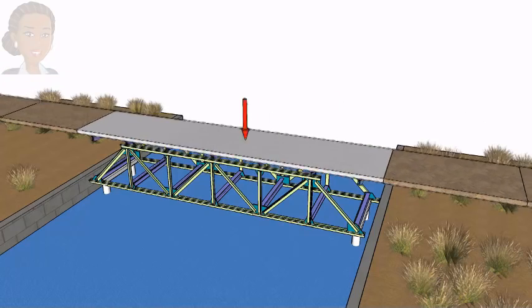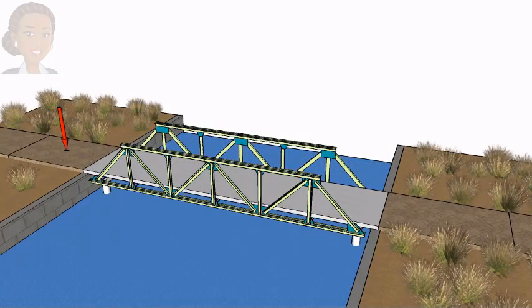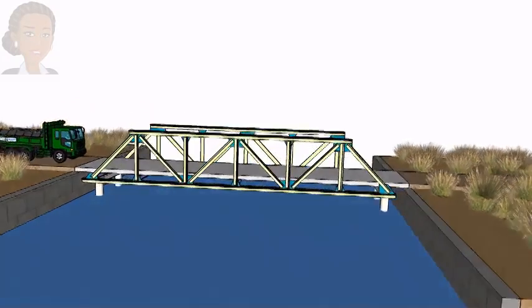We use this moving load pattern to construct the influence line for a truss member. However, in drawing the influence line, we only need to consider the loading cases in which the load is directly on top of a beam. All the in-between cases would be automatically captured by the straight lines that we draw when constructing the influence line. Let's draw the influence line for one of the truss members.